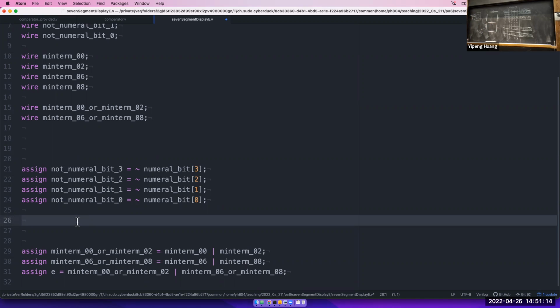Does it light up for 3? Right, if it's 3, the way the 3 is displayed is 3 is displayed there. So A, B, G, C, and D would light up, but not E. Right, so the only digits that E lights up are 0, involving the outer segments. 2 would light it up. 6 would light it up. And 8 would light it up.